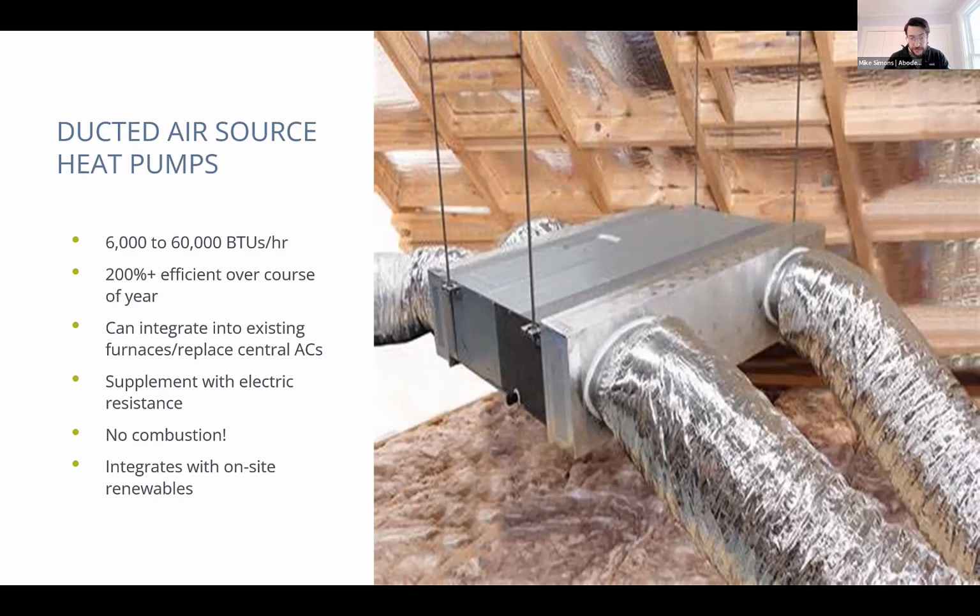The ducted heat pumps traditionally look really, really good when you're connecting them with an energy monitor. The nice thing with the ducted heat pump systems, especially when using it for a whole home, is it has a huge volume of air and it allows the heat pump to likely run at its peak efficiency for the longest periods of time.